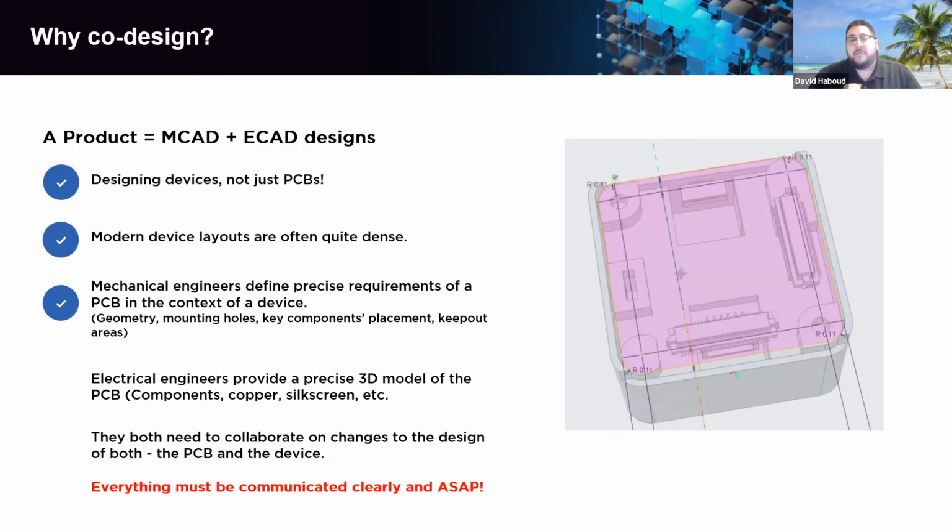If you have a connector in an area that's not allowed, they need to define that. Otherwise, how is the electrical engineer going to know that? It's quite possible that in the context of the single PCB, that component can very well be in that area, but in the context of the entire product, that connector cannot stay in that area. And we're going to look at that a little bit more when we start making this board in the demonstration.